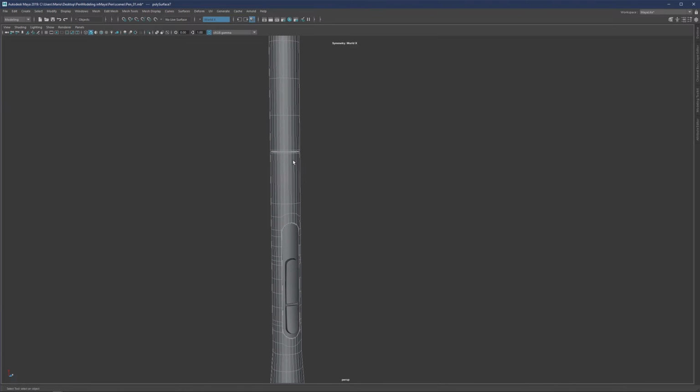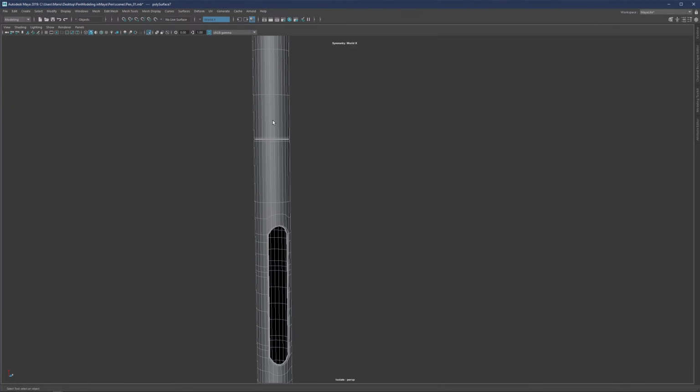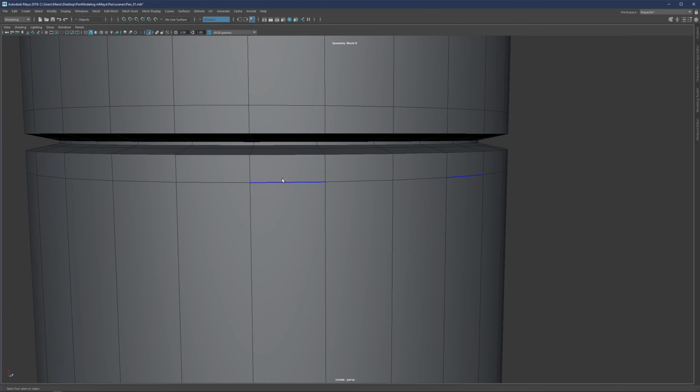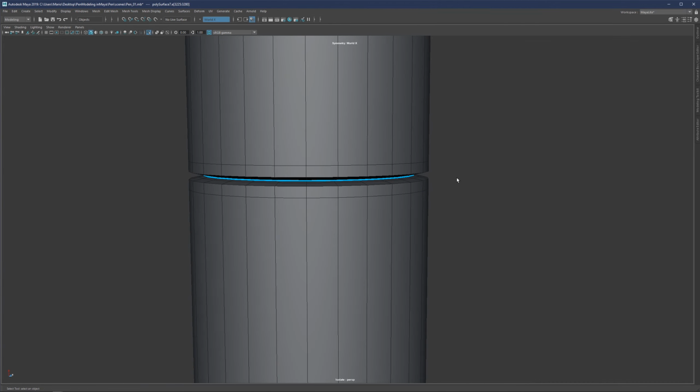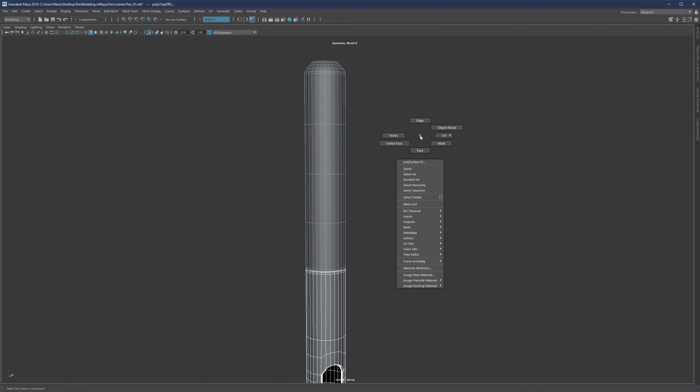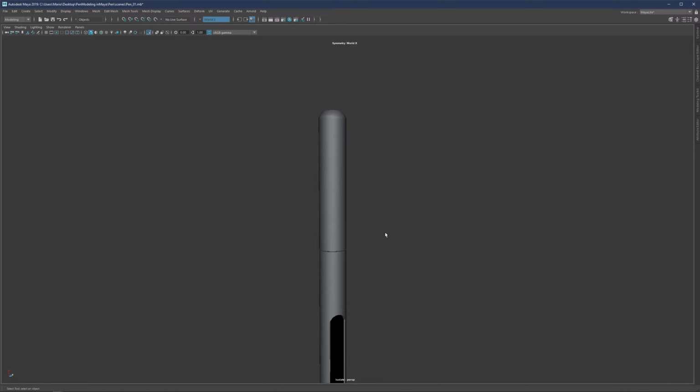Now we can also maybe do the same thing for the top. So again, I'll just Control-1 and click. Create a small little cut here in the middle. Double click on it. Detach components. Q to confirm. Object mode. Face mode. Select this part and extract faces. Hit Q to confirm. Go to object mode. Click away, and there we are. Control-1 to bring everything back. So now we have all these as separate objects.